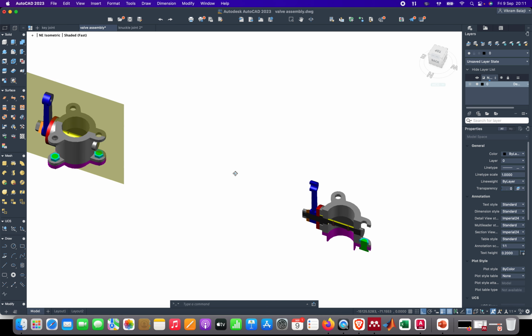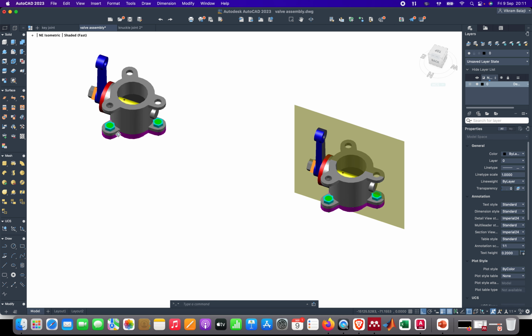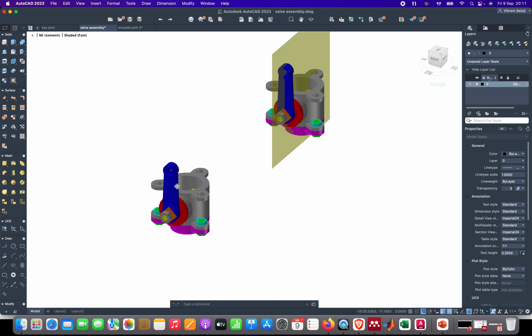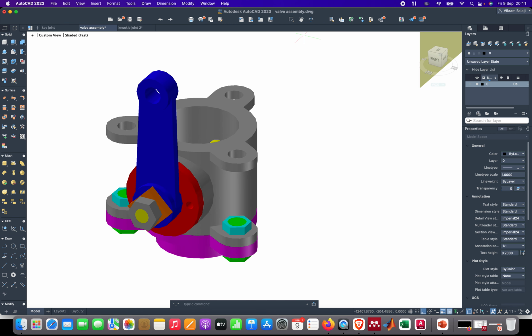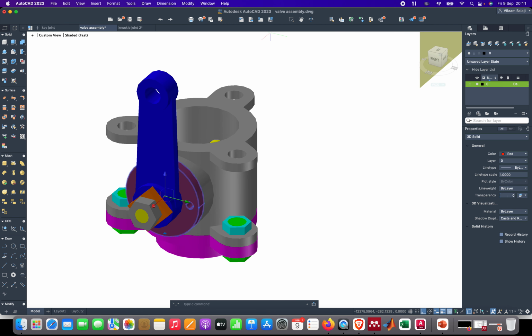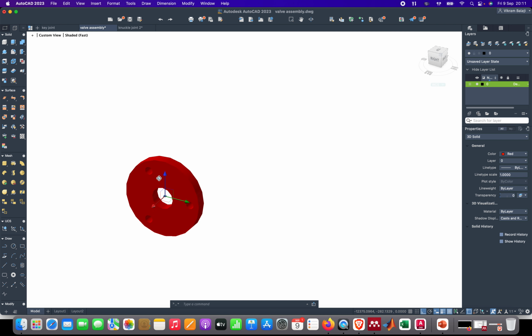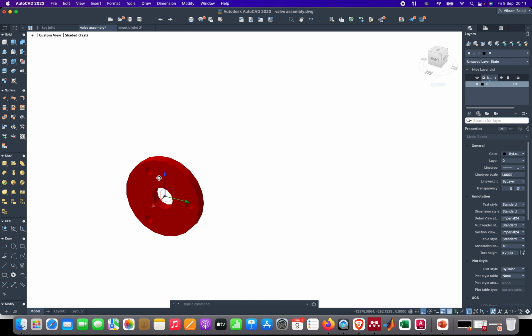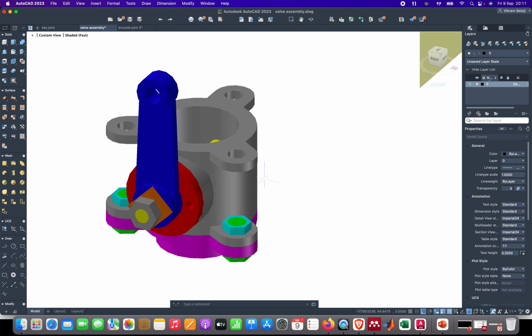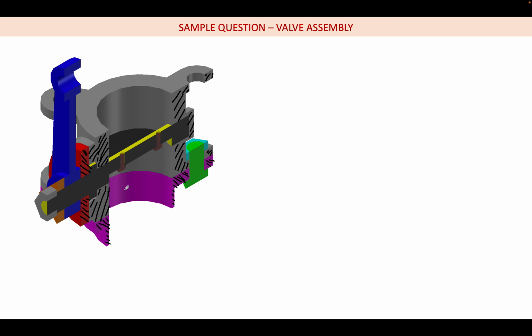So you can see here this also has 3 bolt circles. One is here, another is here, another is here, but the section plane passes through this one, so it is not cutting. Hence we are not able to locate it in this view, since it is a sectional front view or drawing. So sometimes, in order to do that, we can go for another kind of view, so it may be another section plane only that we are able to see.